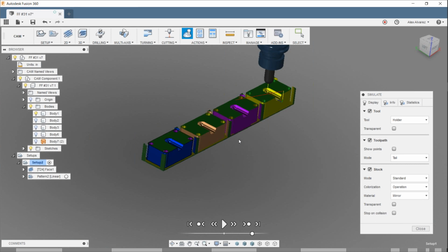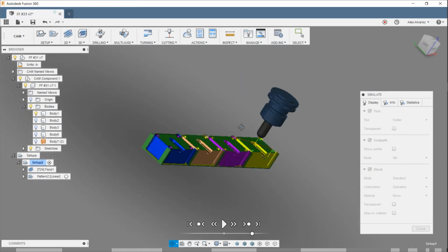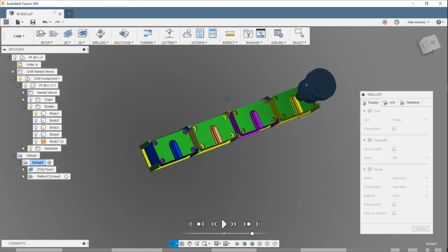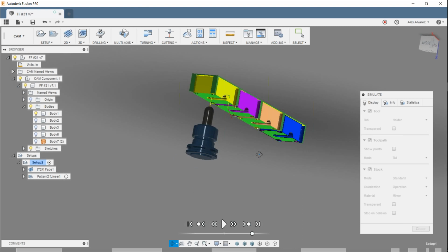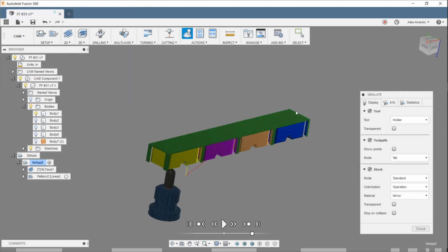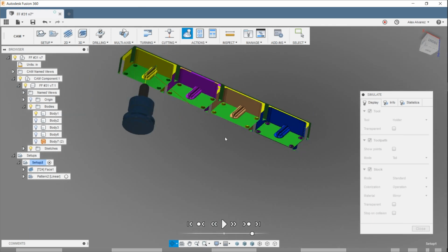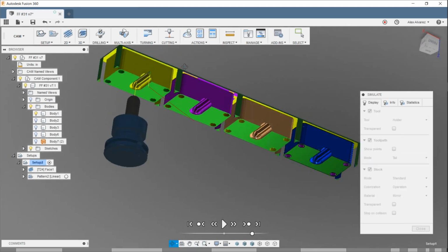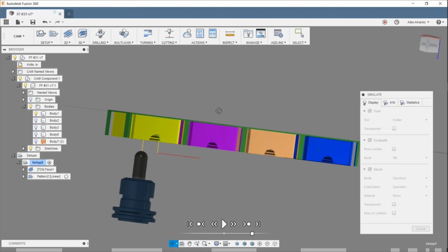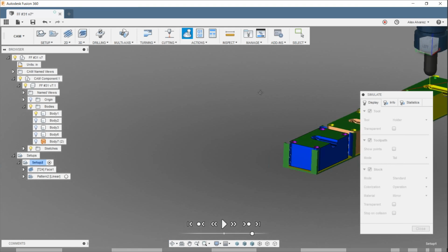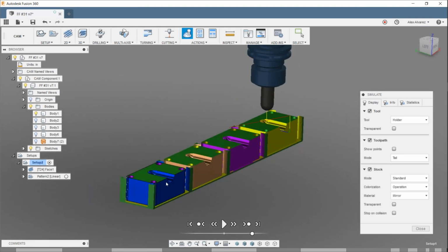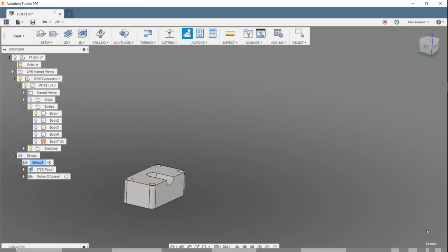Now, depending on the work holding that you have for the second operation, I know a lot of people use glue and tape to fixture that. You can do some sort of vacuum holding as well, and then just machine off that top hat. These little columns here, we don't really care about because they're already outside of the stock. But that pretty much covers the patterns here. So that's how you would create a pattern when you have a given stock length and multiple parts that you want to create from that.